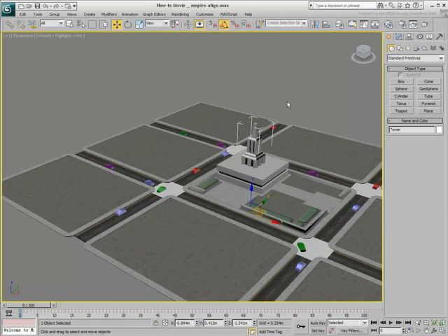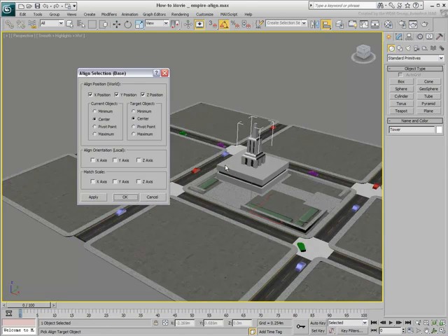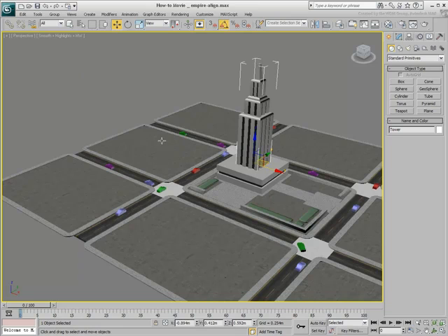Often you need to align two objects using varied constraints. As an example, you may want the bottom of the tower to be aligned with the top of the base. In such a case, you are looking at a height-only translation based on the z-axis. With the z-axis alone enabled, you can force the minimum value, the lowest z value of the tower, to be aligned with the maximum value, the highest point of the base. Usually you do not need to exit the dialog to force changes.